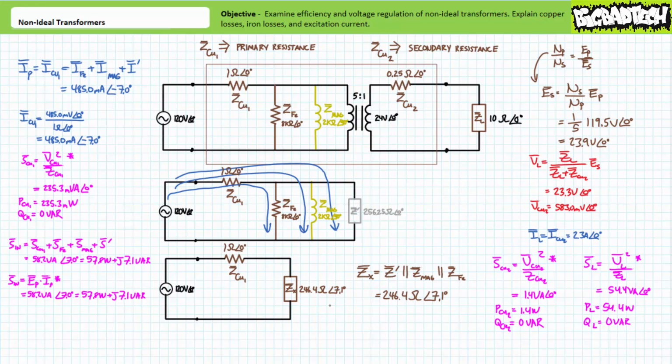Our previous calculations using reflected impedance demonstrated a consumption of 55.7 watts of real power. Accounting for rounding imperfections in the secondary, you'll note the summation of power consumed by both the load and the series resistance is also roughly 55.7 watts. More to the point of this particular lecture is the efficiency of this larger system with respect to the transfer